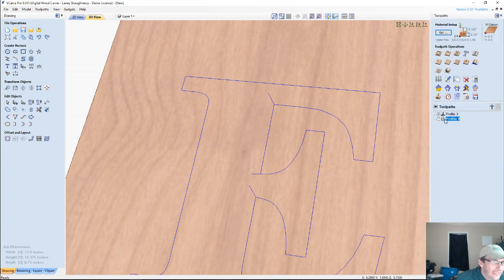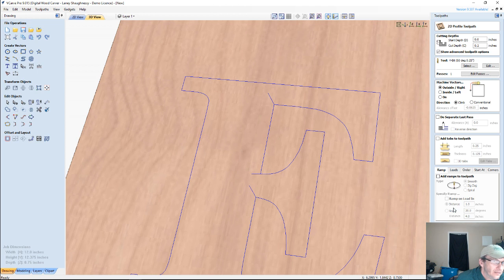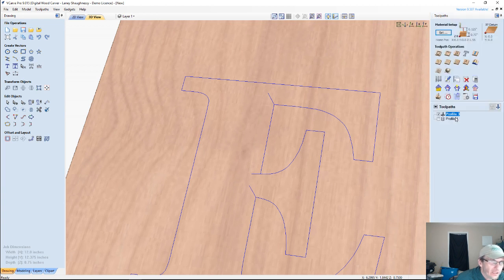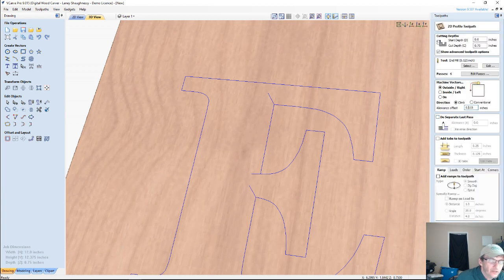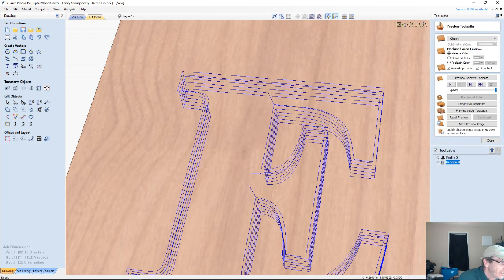It was actually telling me in that corners tab what the allowance was for my cutout tool, what allowance I needed to use based on the bit and all of my parameters and my sharp corners and everything. It was actually telling me what offset to use. And if I would have come in here and created using the offset it told me to use, I would have been perfectly right on instead of having to sneak up to the cut. Okay, and I was sitting there trying to type into that box like it was an entry box, and it's not.